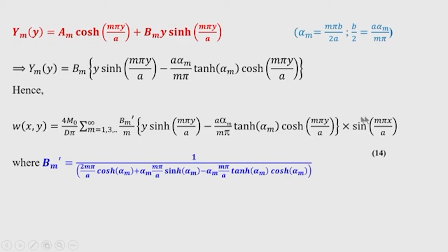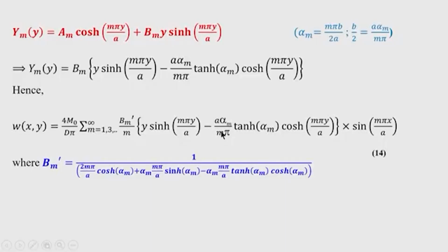So, once you get the deflection of the plate, then you can find the shear forces, if required, Qx and Qy. You can find the Kirchhoff's shear, that is the shear found after combining the vertical shear force with the shear force contributed by the twisting moment. So, these two force effects are combined to give a shear which is due to Kirchhoff, and therefore it is known as Kirchhoff shear. So, all these distributions you can find out.